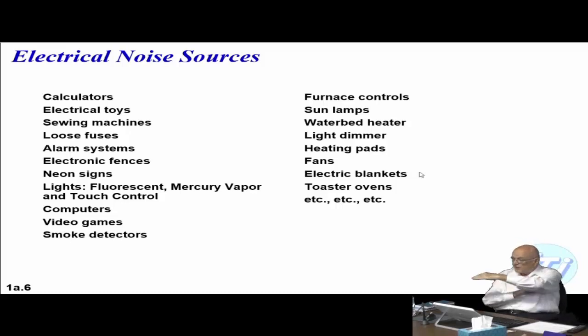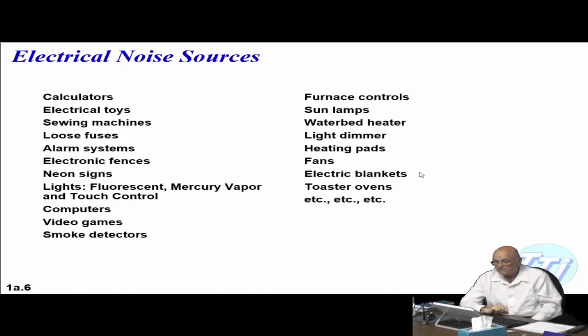You know how you have benches around a room with equipment and interconnecting cables. So they decided to move all of that to the center of the room. Drill about 5 or 6 holes and put in grounding rods specifically at that point, right directly through, trying to find a common point. You don't end up with a ground loop, because you can actually end up with a ground loop problem on your benches as you scatter them around the room.